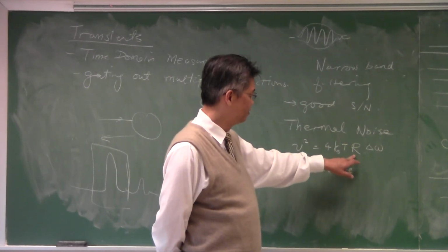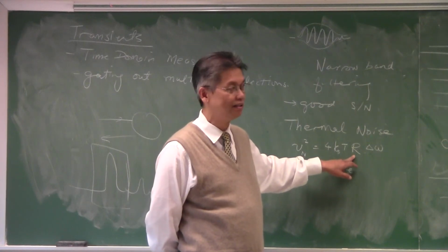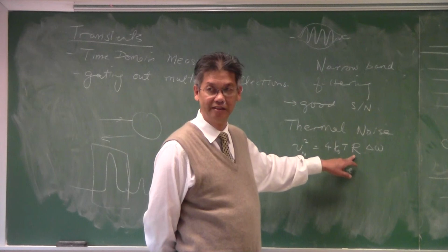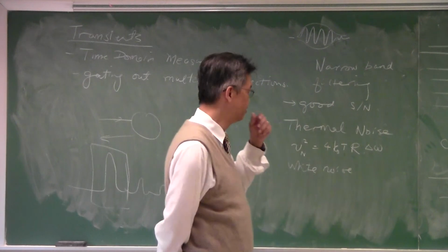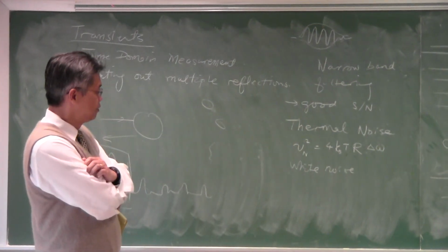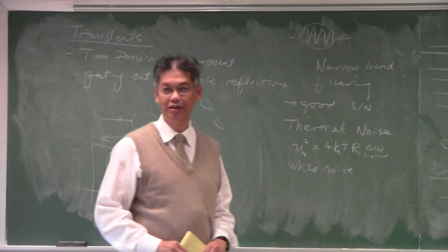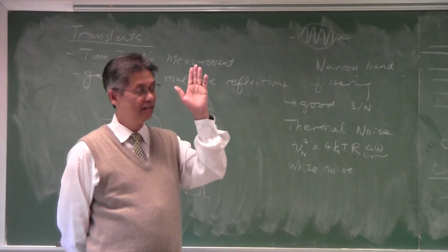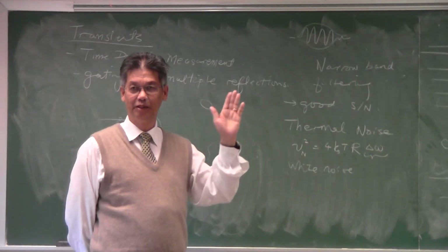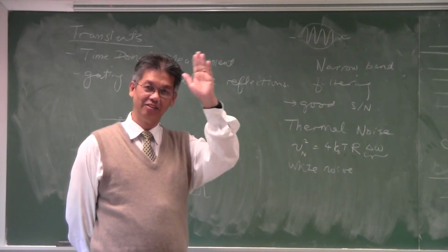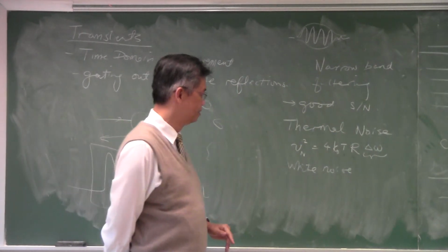So one way to get rid of the resistive noise, thermal noise, is to use superconductivity. If you have superconducting materials, they generate less thermal noise. Of course, you can cool the temperature too. Okay, make the temperature low. So one way to reduce this thermal noise is to make the bandwidth as small as possible. Do narrowband filtering. So you design extremely narrowband measurement systems by heterodyning systems, super heterodyning systems. You probably have to learn how those things work. You can actually do a microwave measurement at kilohertz bandwidth by heterodyning the system.